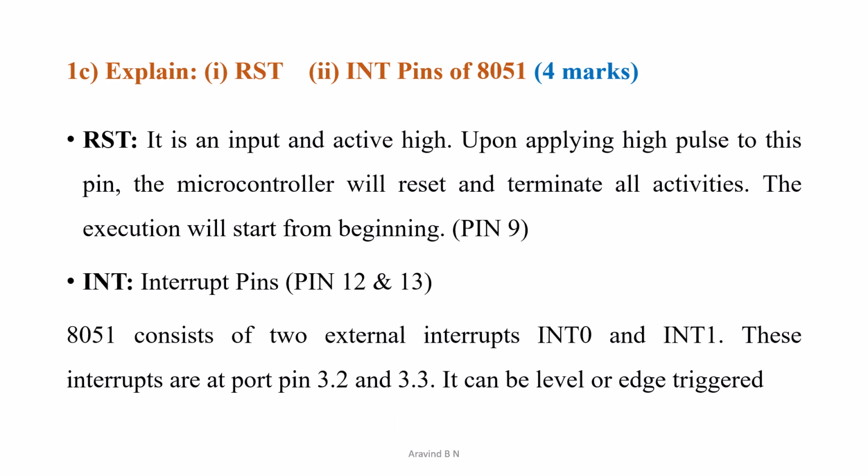1C, explain first the RST pin, second the INT pins of 8051. This is for 4 marks. The RST pin is an input and active high pin. Upon applying a high pulse to this pin, the microcontroller will reset and terminate all the activities, and this is pin number 9.